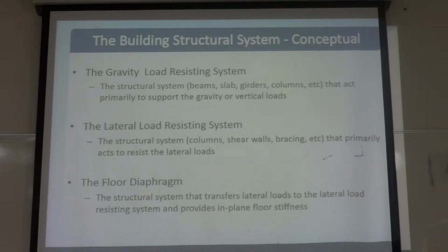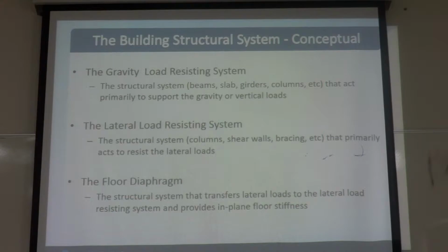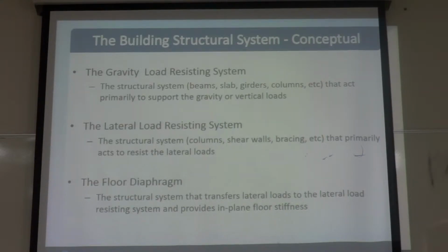Actually, the floor diaphragm is a slab, a gravity slab only. So normally, when you design the slabs, we design only for the vertical load, out of plane bending moment and out of plane shear. People normally do not design for the in-plane forces to transfer the inertial forces through the diaphragm. Those things we also have to check in the seismic design.